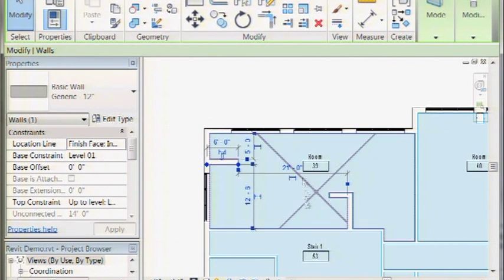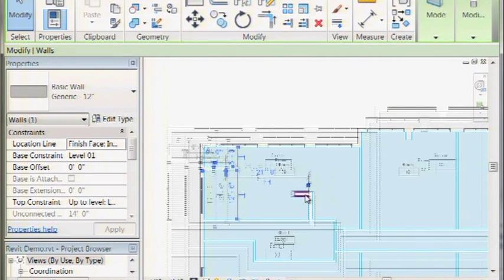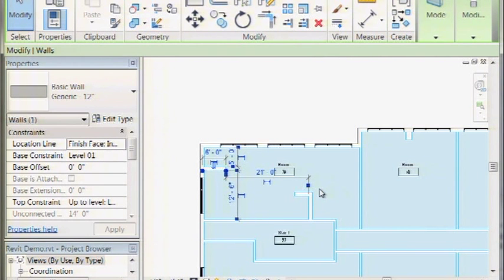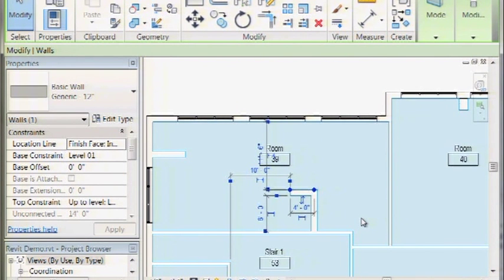Because in the virtual environment, this would actually be its own room. Then you would have holes here and here if it was going to be two walls and then an opening. So these become shading surfaces, and you have a decision. Do I want this to become an individual room on its own and add a room separation line, or do I just want to ignore these? In most cases, you're just going to ignore them.